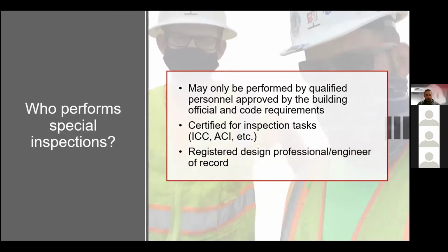So we did touch base on this a few slides ago, but who performs special inspections? It may only be performed by qualified personnel approved by the building official and code requirements. They're certified for the inspection tasks, ICC, ACI, whatever certification they need for that task, or like I said, the registered design professional or engineer of record.